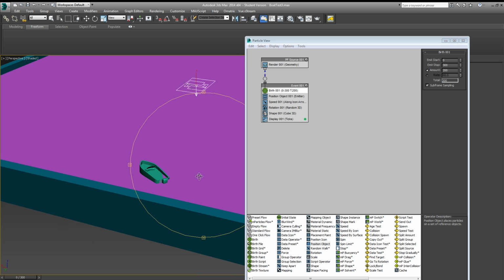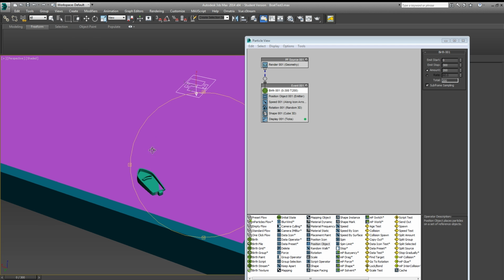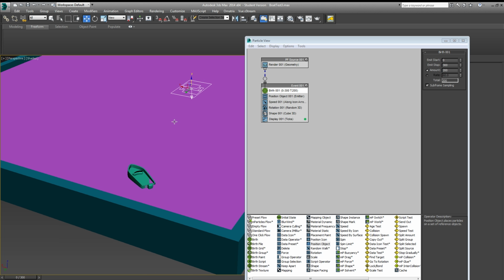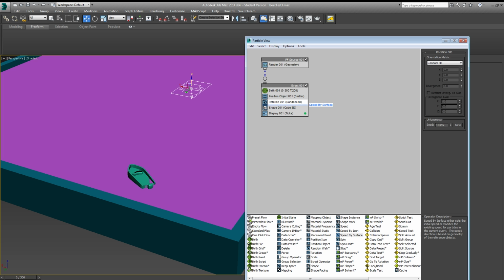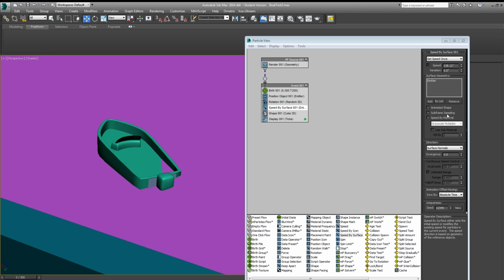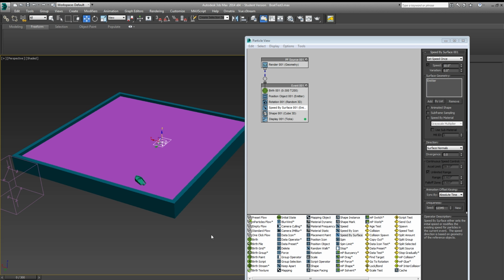and what I want is for these particles to actually lock onto the water as it's moving through. So what I'll do is I will also turn on speed by. I'll get rid of this speed right here, and I'll turn on speed by icon. Where is it? Speed by surface. And I'll add that emitter as the surface speed. And then I'll set this down low, I don't know, 10. And we can try it again. We can play it again and see how that's looking.